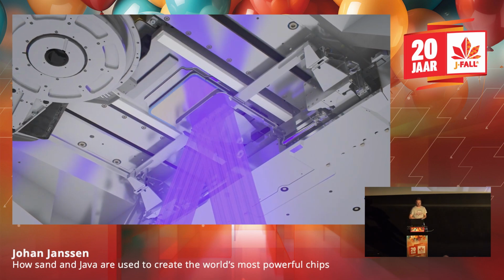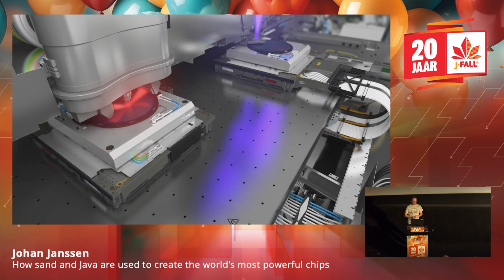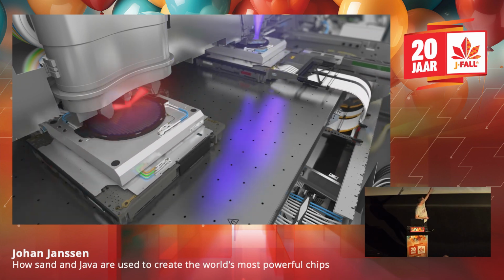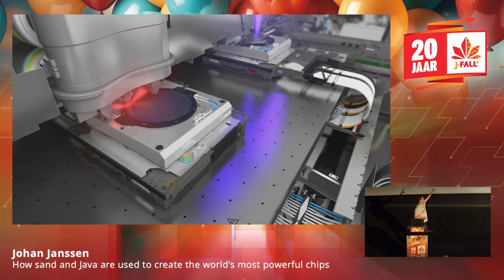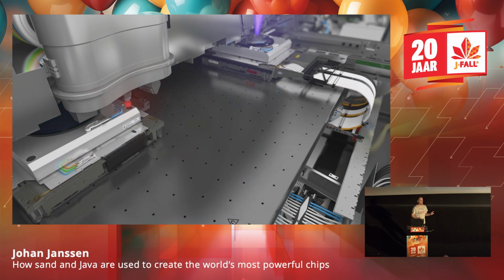And then it looks like this, the reticle part. And then it goes like this. So on the left, you see the machine with a wafer. Here it's measured so that the position is okay, and the one next to it is doing the printing. This speeds up the process, because otherwise we need to wait until it's positioned properly before we can start printing. So that's why we do 2 wafers at the same time.